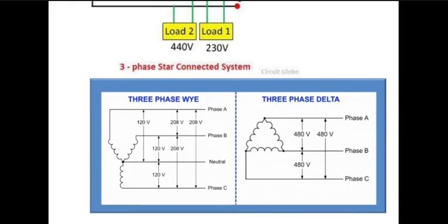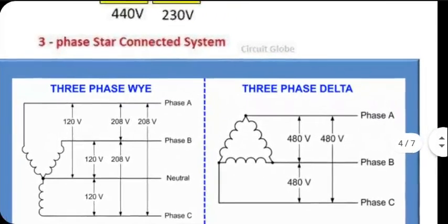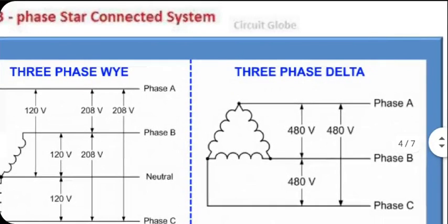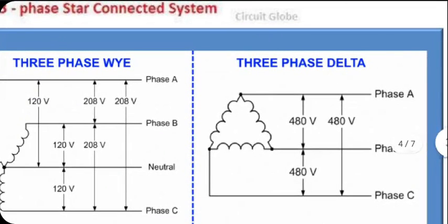Now, another possibility is to connect the 3 generators with no neutral, instead having what they call delta connection. You see the rightmost side. They are connected in tandem. That means one end of a generator is connected to the other end of the other generator. There's no common point here. There's no neutral possible here. This is called delta connection, obviously, because the shape looks like delta.